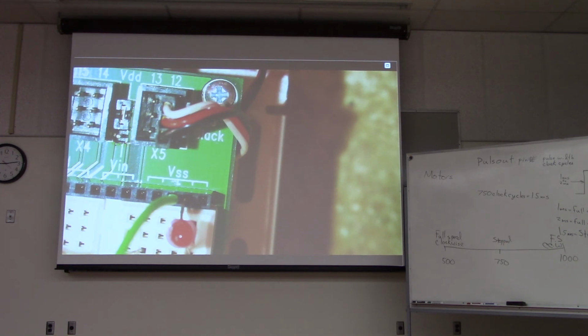That's what happens in cars. The lower voltage from the battery is connected to the chassis of the car. That's why when you're jumping a car, you can connect the positive jumper wire to the positive terminal of the battery, and you can connect the other jumper wire to the chassis of the car, because the chassis of the car is electrically connected to the other terminal of the battery.